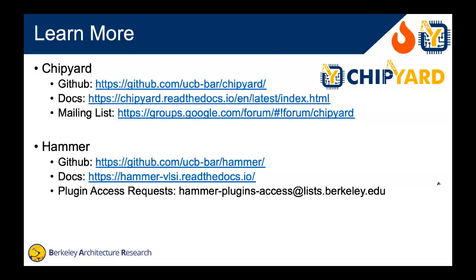Yeah, so our Chisel generators have lots of parameters you can set. How many buffers do you want on your tiling crossbars? How deep should your FPU be? All these things that you get a report out of Hammer. It tells you your critical path here or there, or you're having congestion here. Then you feed that back into updating these Chisel parameters.